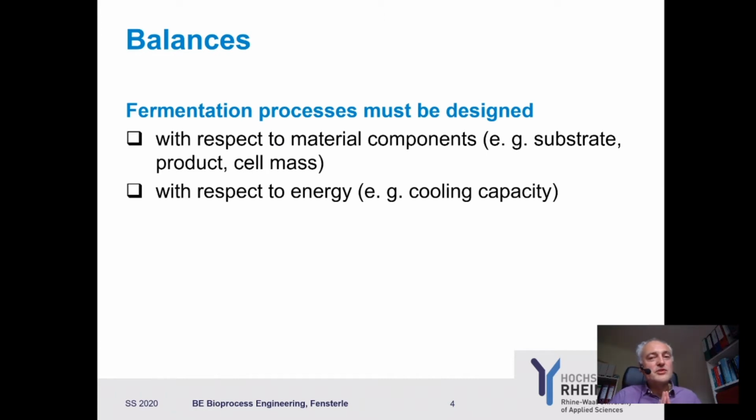Of course, bioprocesses are exothermic reactions, although in the lab you usually have the flask on a stirrer with a heater, or in an incubator at 37 degrees. The reason is simply that for most of the time there is almost nothing inside; exponential growth only shows up at the end. But in a large bioreactor, a growing microorganism produces heat, and you need to remove it. It's like when you run in the forest: you produce heat, and you need to remove it. The same is true for a bioprocess.